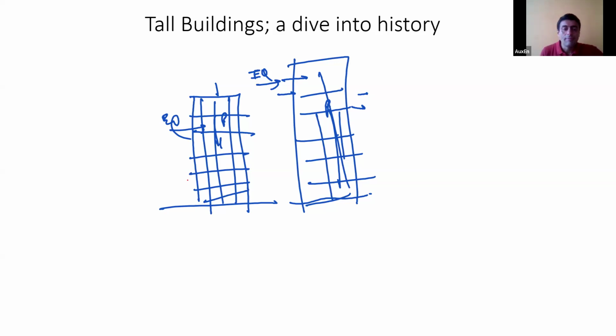Maybe if you want to increase the design life, the return periods that you consider for, let's say, wind, may have to be taken as higher. So you may have to look at some higher return periods, maybe a 120-year return period or a 200-year return period. You design for that for strength. So if you are taking more design life, you have to increase the return periods for your probabilistic loads. Same goes with earthquake also.